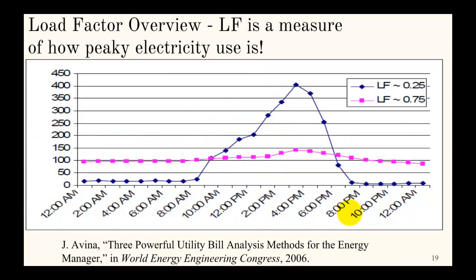Good. So now let's talk about load factor for just a second. Remember, this is the load factor for a day, but usually you look at monthly load factor when you're looking at your utility bills. All load factor is has nothing to do with usage. It's a measure of basically the shape of your usage profile, and it's a measure of how peaky your electricity use is. So a low load factor means your electricity use is relatively peaky, and a high load factor means it's relatively flat, and it's going to be between 0 and 1. So this just shows you a visual example of that.